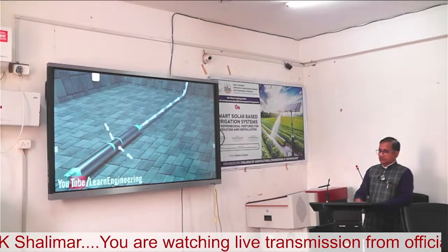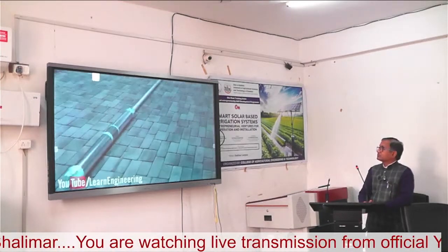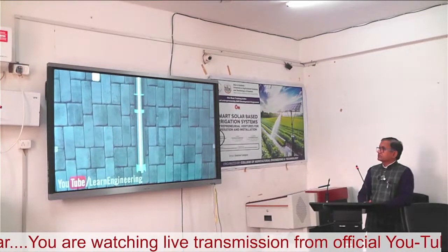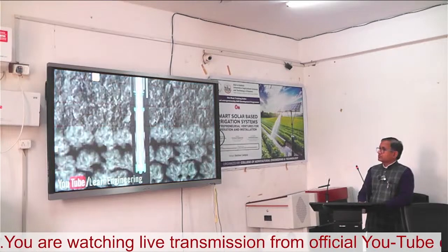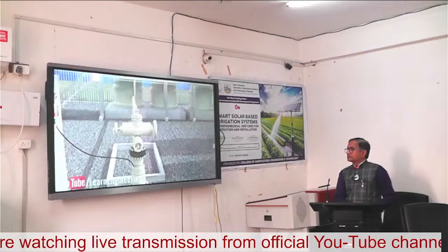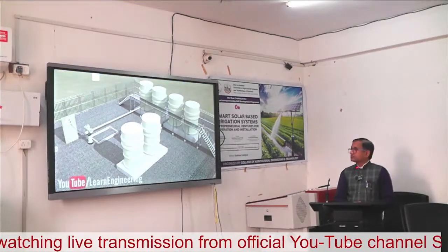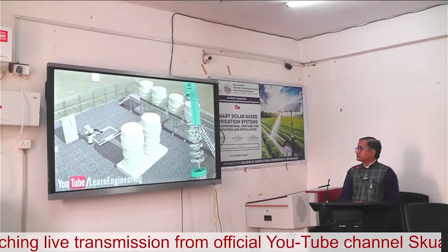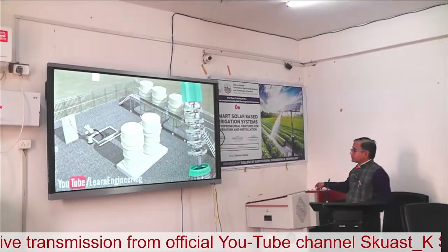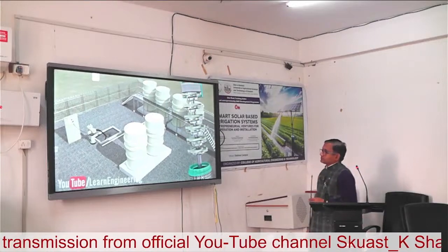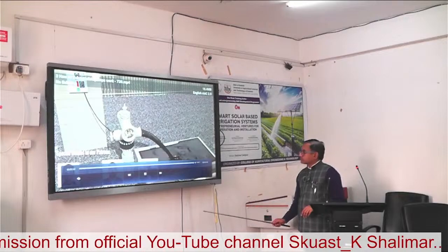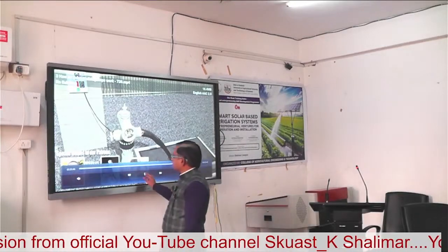The high pressure head, flow rate characteristics, and the ability for it to be immersed completely in the water make submersible pumps an ideal choice for bore well lifting, firefighting, and oil well lifting. 90% of the oil wells in the world require some kind of artificial lift to achieve an economic flow rate. There is no narrow flow region in the impeller and diffuser section of submersible pumps, and this fact also makes submersible pumps the ideal choice for wastewater pumping and lifting highly viscous fluids. Moreover, with a specialized design, submersible pumps can even be used for slurry pumping.